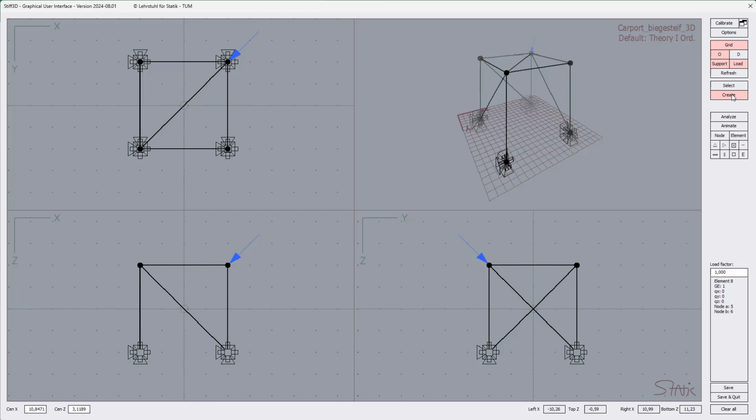That is what you have to switch on just to be able to create items. So to be more specific, without further selecting what you would like to create, node or elements, you have to activate these guys also. Here you see activating node. And if I just go here with my cursor into one of these views and press the button, you see what I did. I created a node. If we try it a second time, you see I'm not successful, simply because you see this button has been deactivated in the moment when I just have created a node.